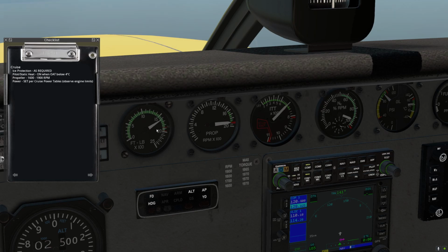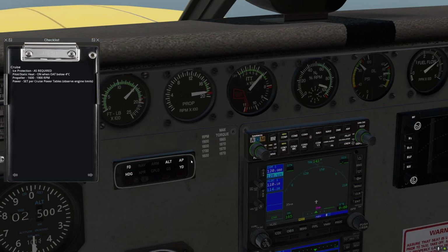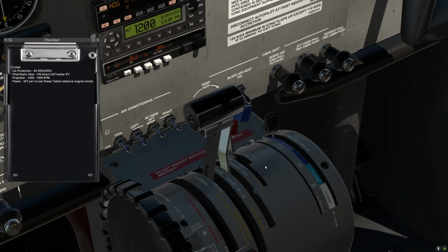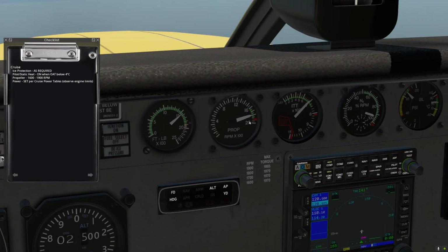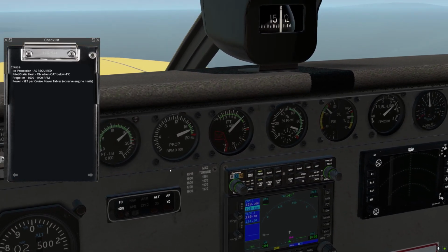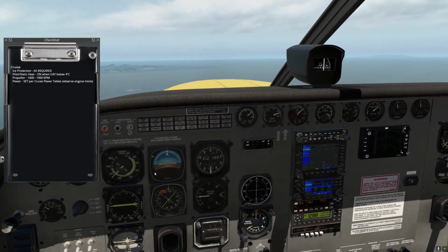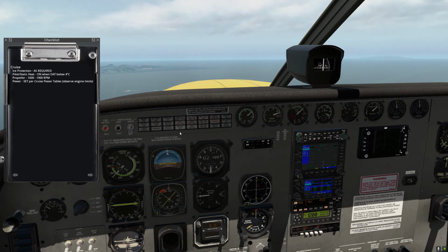So I'm going to pull the power lever back to 1500 foot-pounds of torque, and I'm going to bring the blue propeller lever back to 1750, right about there. And if you're lazy, you can use just whichever comes first, 1500 foot-pounds of torque, 700 degrees ITT, or 350 pounds per hour fuel flow, which is a good rule of thumb. So propeller and power are set.